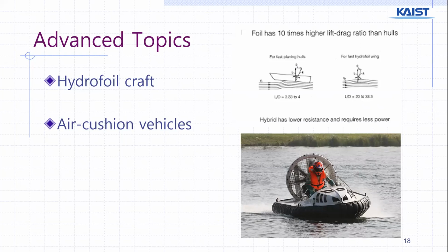The hydrofoil craft on the top there essentially allows for less wave resistance, or even you could say friction resistance as well. It helps lift the ship out of the water. It can be a hull or the wing that is the hydrofoil component that allows the ship to be lifted out of the water. The pros, as you can imagine from lifting it out of the water and decreased friction, are that the ride can be very smooth, and there's more fuel efficiency as there's less fuel required to make it move, and reduced drag.